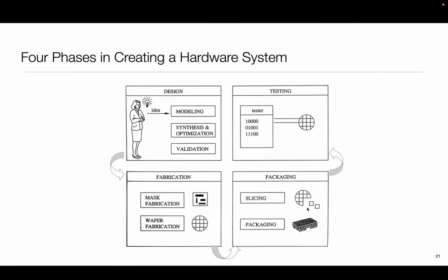And what these guys are doing is they take these little pieces of silicon, flip them, and put them directly on a big piece of silicon. Okay, so this whole thing is called chiplets. These are chiplets, and chiplets are sitting on a piece of silicon, as opposed to being individually packaged. This has become a hot way of designing systems, and actually the M1 processor in my laptop is an example of a chiplet-based system. It has a small number of chiplets, all bonded, all kind of glued, if you may, onto a piece of silicon.